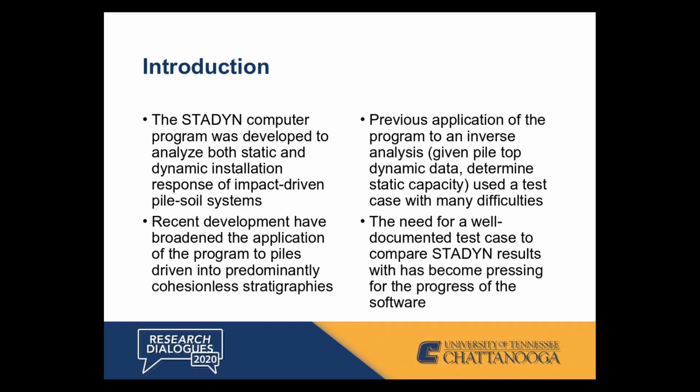We have to consider the static response, like a static load test, but ultimately we have to think about what load we're actually putting on the foundation, and the dynamic installation response, which includes what happens while the pile is being driven, in this case by impact pile driving.